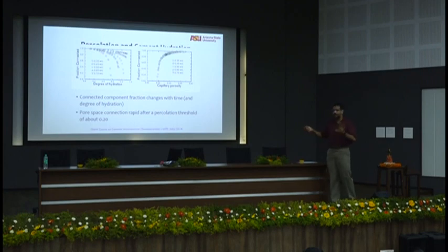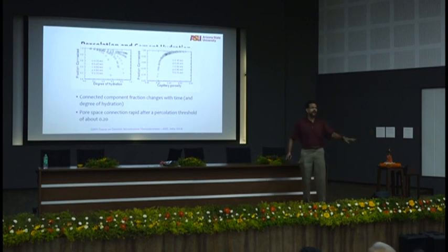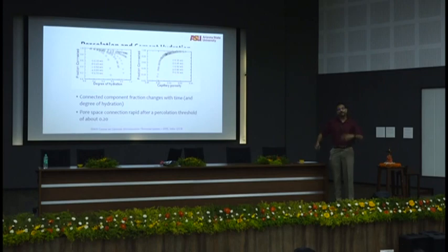I want to spend some time on this picture to give you the real essence behind why concretes fail, why durability is such a big issue, even though there are a lot of concretes specified in India, and people say 0.5 water cement ratio is okay. You see that? I tell all the time, no, anything more than 0.4 is not okay, purely based on this point. And then they'll say, no sir, we have put in 20% fly ash.